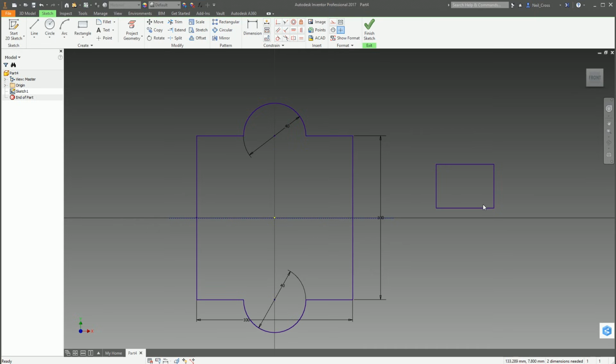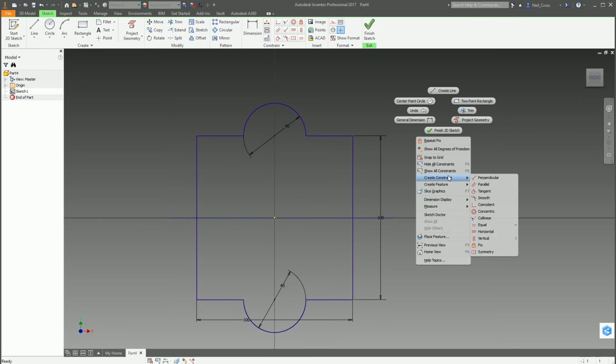But when you do that, you are completely limiting what you can do with that in the future. I mean, you can delete the constraints. You can select the line, select the padlock, press delete, and that will remove the constraint. It's a cheat, but it can be helpful for some scenarios. Back to create constraint, the final one we've got is a symmetry constraint.